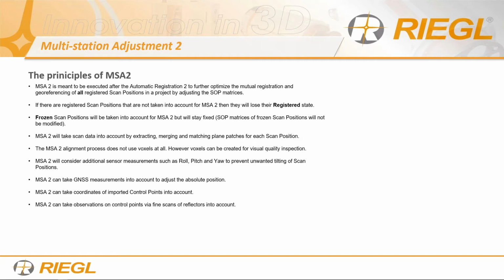So if you strategically set your scan positions around the project and you control those ones, everything else you scan in the middle can be fixed to it. So instead of tying down to 6 survey control points out in the project, or 10 or 20, whatever the case is, you can make use of the plane surfaces. So in a sense, those are also considered control, right? Because you're using it as a base, and then you're tying different scan positions to it. So you're using much more control from the point cloud versus just the survey control. So that's just another scenario.